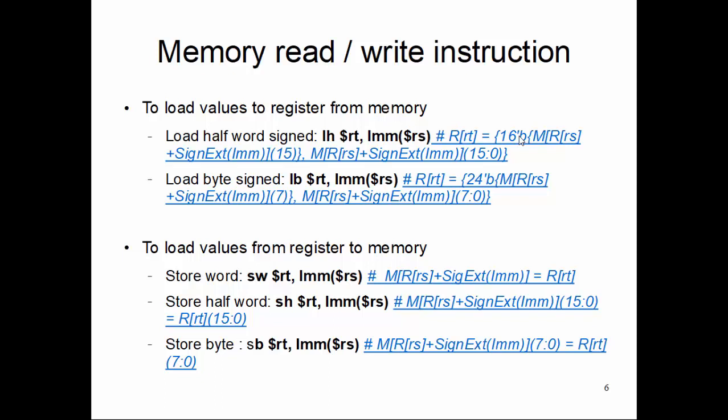There is nothing called an unsigned or signed notion because we are just interested in storing a bit pattern. It is upon the usage of the bit pattern. When you load it back, then you want to think of this sign notion. Are you treating that 8-bit or 16-bit as signed or unsigned? Only loading cares about this, right?